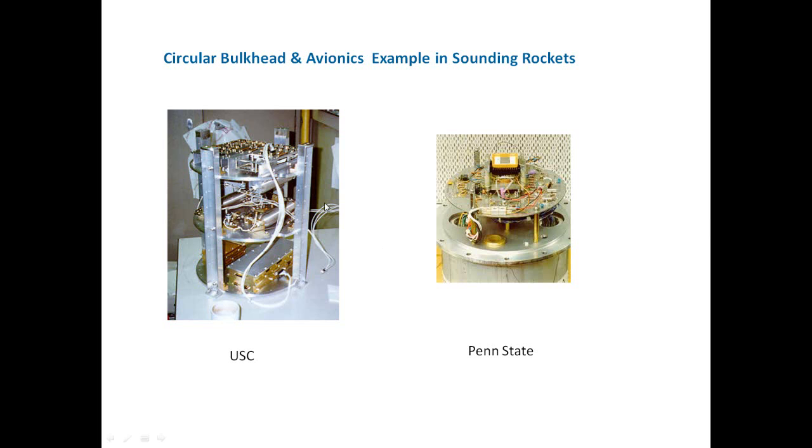So if we were doing an analysis, we would say, okay, we have these circular plates, and there's so much mass riding on each plate or mounted to each plate. Then we would take that mass and smear it uniformly over that plate.